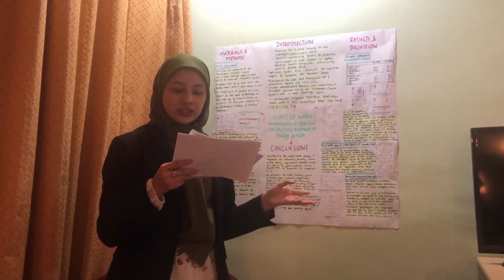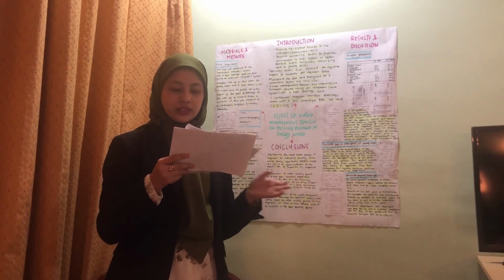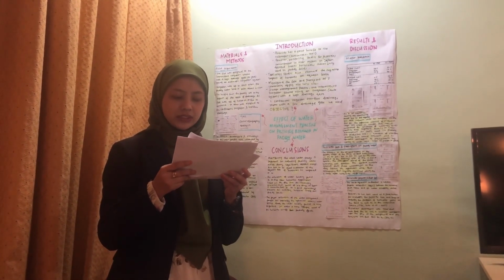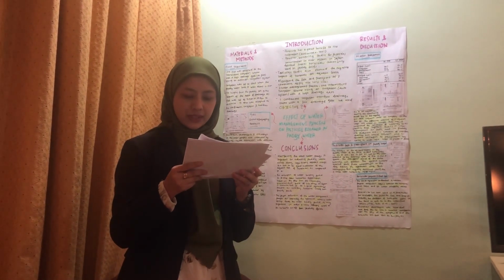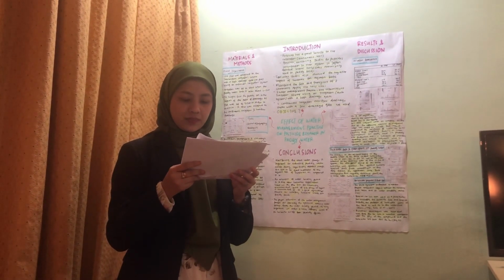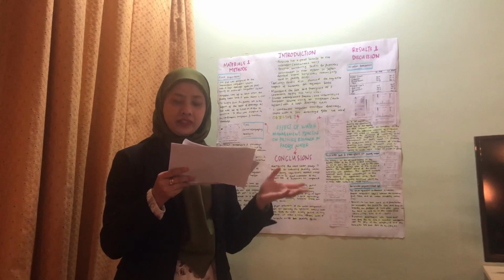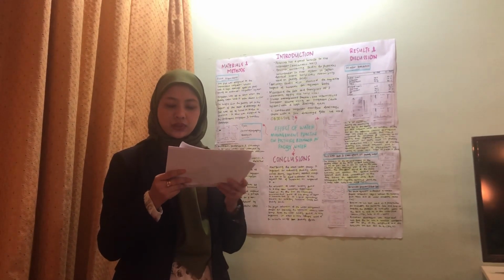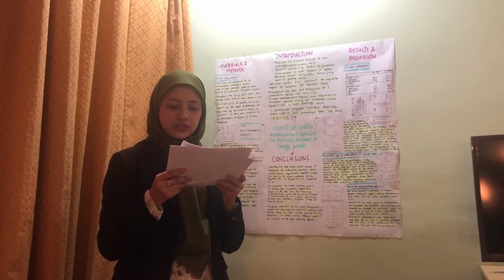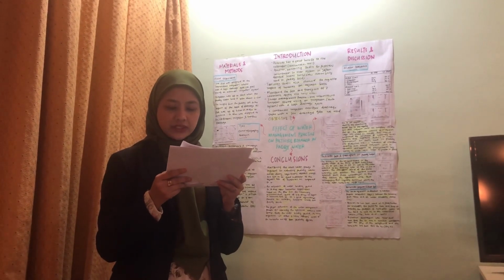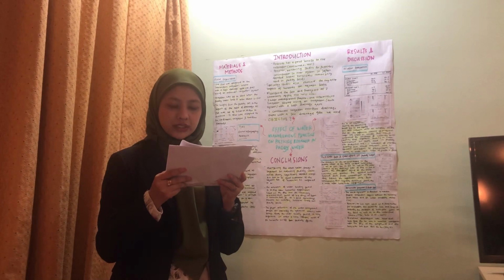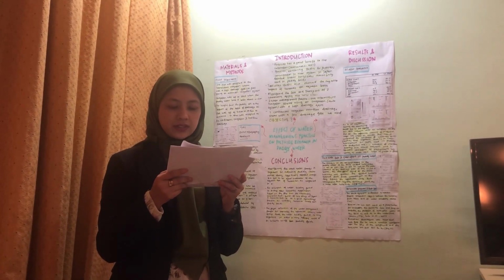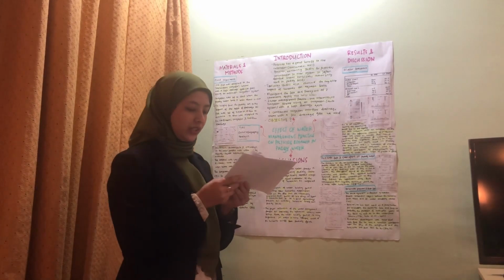The herbicide concentration in the drainage water from the CI plot was always higher than the concentration measured in the composite sample of the same sampling date, and the average difference was about 70% throughout the monitoring period. This phenomenon results from the structure of the plot, with irrigation water coming in one side and drainage water going out the other side.